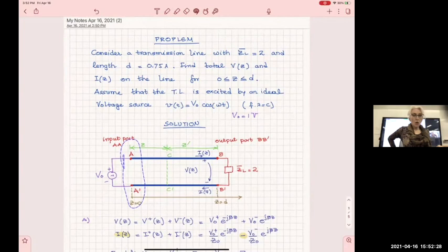If my source has an internal impedance, it's going to limit how much power goes in, because part of it is expended internally in the source. The source has an internal impedance because the source is not just a transistor. A transistor cannot produce anything without all of the circuitry around it, and that circuitry takes up some of the power. That's why internal impedance is there.